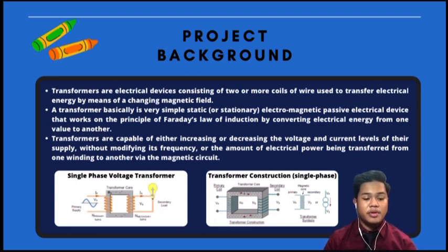Vp is the primary voltage, Vs is the secondary voltage, Np is the number of primary windings, Ns is the number of secondary windings, and Φ is the flux linkage. Notice that the two coil windings are not electrically connected but only linked magnetically.